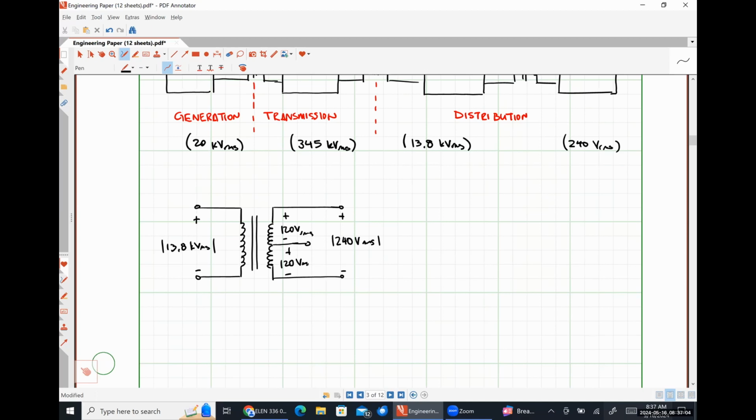So in your home, connected to your circuit breaker, you have access to either 240 volts, positive 120 volts, or negative 120 volts. But there is literally no discernible difference between the positive 120 volts and the negative 120 volts, because the overwhelming majority of simple loads don't care about that 180-degree phase shift, right? The split is located on the transformer, but it's also physically in your circuit breaker panel.